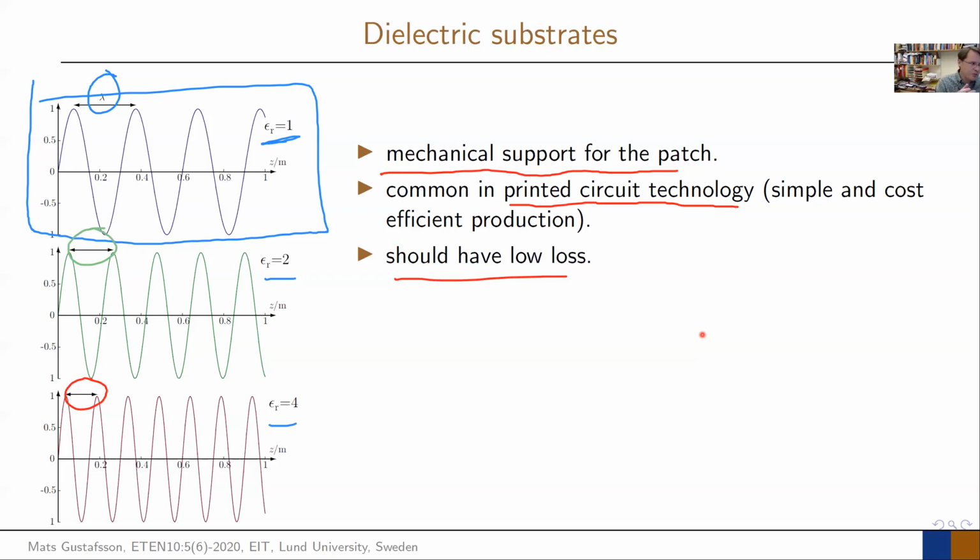And you have learned something about antennas. And what is the main thing we learn about the size of typical antennas, like the dipole? It was that it should be half a wavelength. And now if you put your antenna in a dielectric, of course, maybe it should then be half a wavelength inside of the dielectric. So you have to compensate for what the wavelength is. The wavelength that the antenna actually experiences for this electromagnetic field. That is what we will need to use.